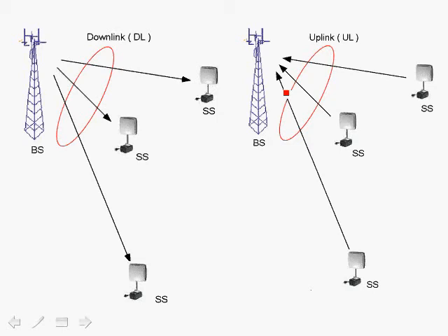We highlighted that a little bit before. And the case is that if in fact all subscribers transmitted at the same power, the nearby transmitters would be received with a higher power than transmitters that are further away. And of course that is not good in the sense that you would have these higher power carriers dominating, affecting dynamic range and also leaking into the carrier slots of the other users. So we have to do power control.